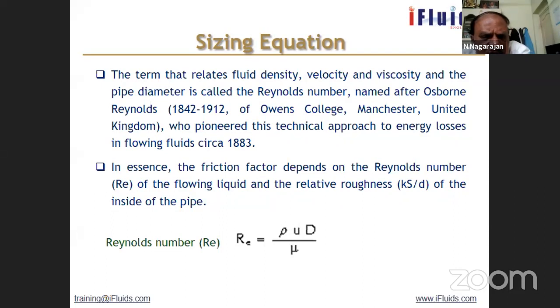So in compression, you will have isothermal compression, adiabatic compression, etc. It means when you compress the gas, the pressure increases, and at the same time the temperature also increases. Physically, you understand gas molecules are spaced apart. When you compress, what happens? The molecules are brought closer. So when the molecules come closer, the collision is more, and the energy dissipation is more.